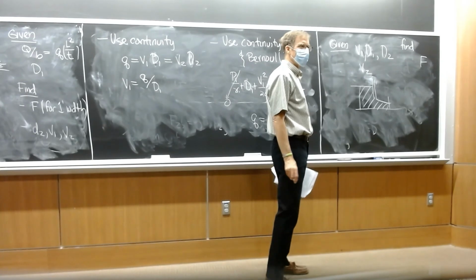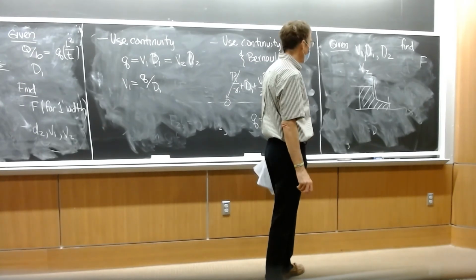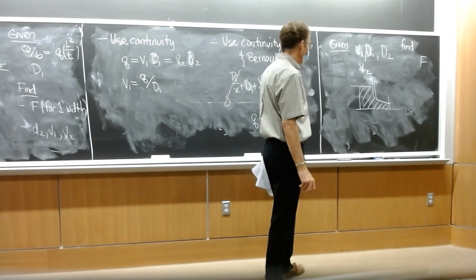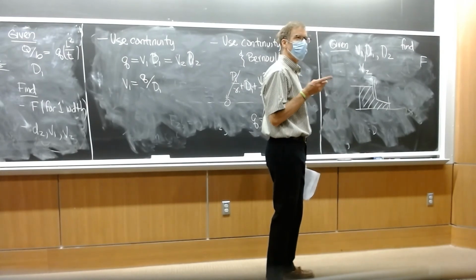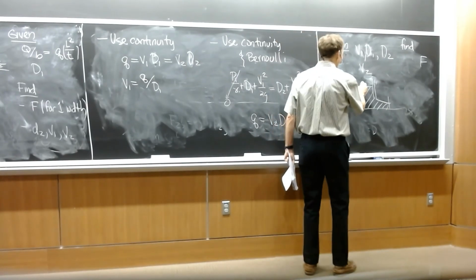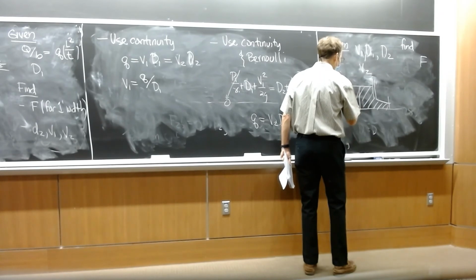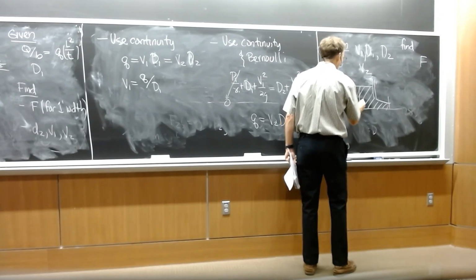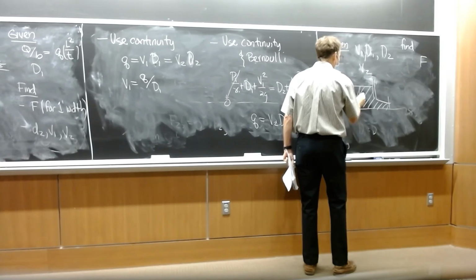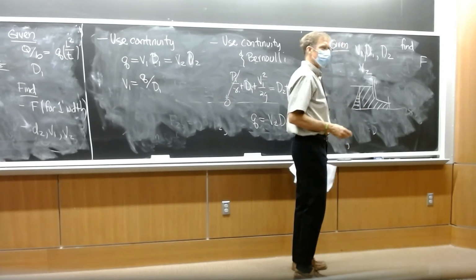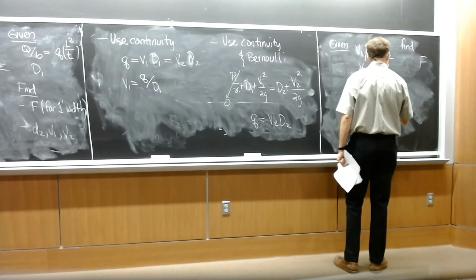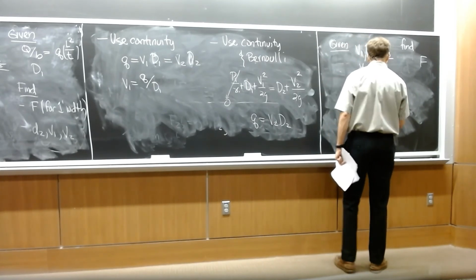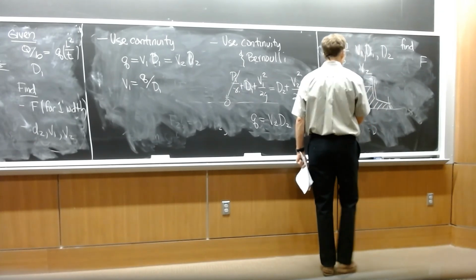So, all right, there's our control volume. And what's important to note is that the external forces on the control volume come from the pressure force that occurs in the water upstream and downstream.